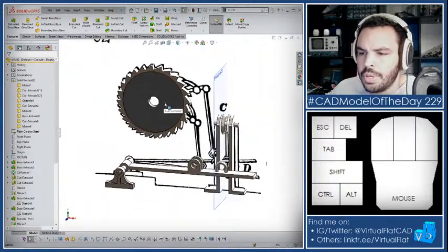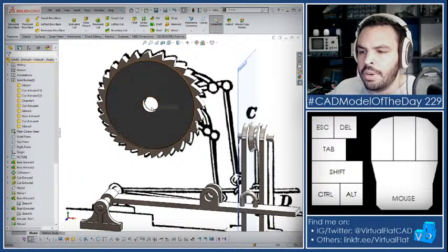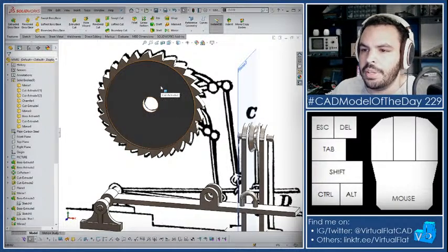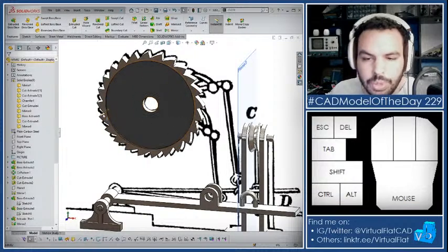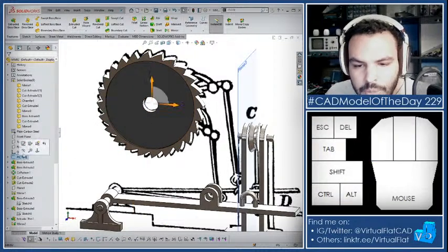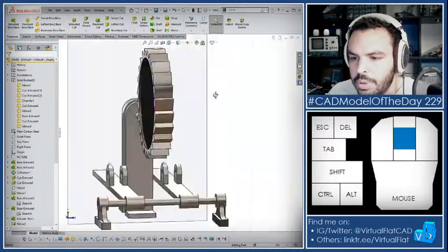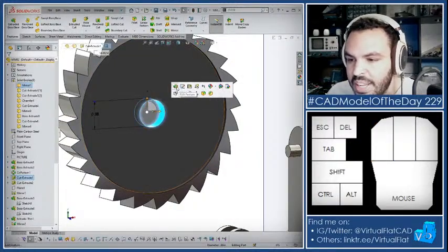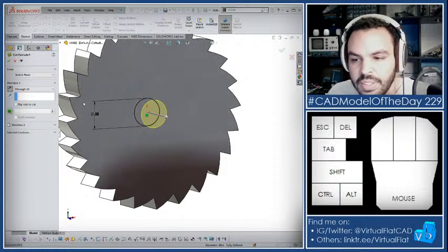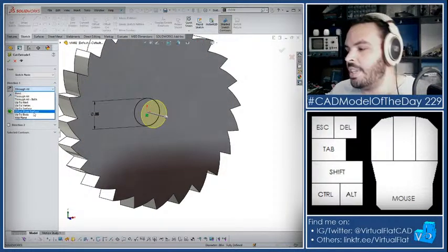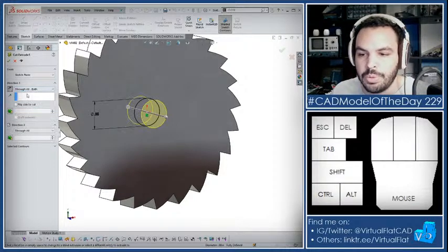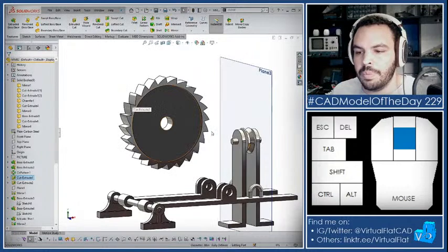Let me start by making an arbitrary length bar for this ratchet wheel to rest on. So let me hide the picture just to see. Oh, this extrude did not do its thing. Oh, yeah, because I changed it from blind to mid-plane, I need to change it from through all to through all both. That's what happened there.